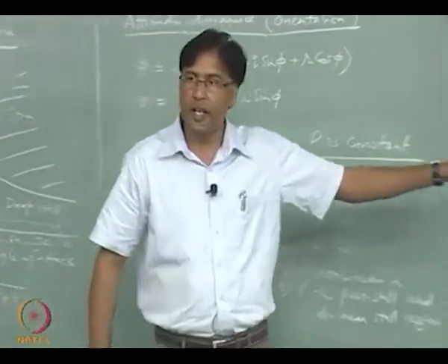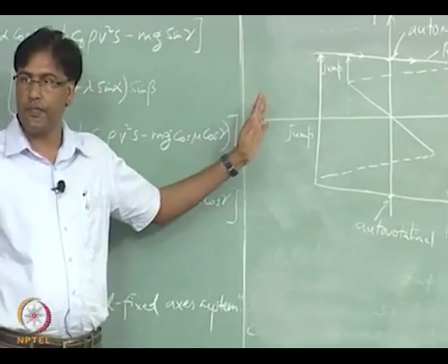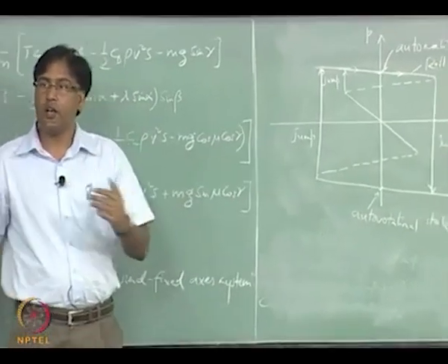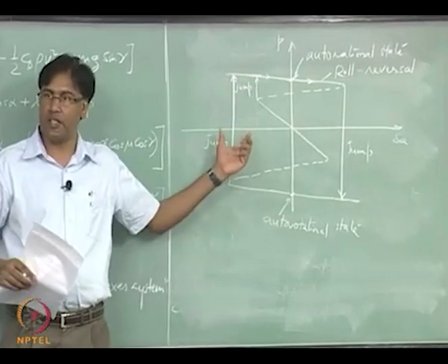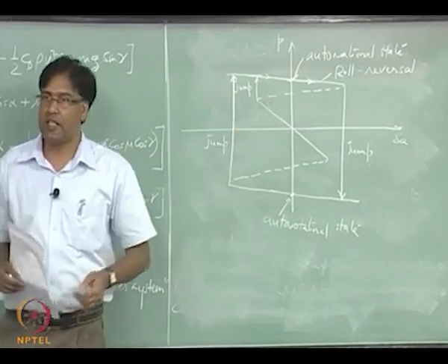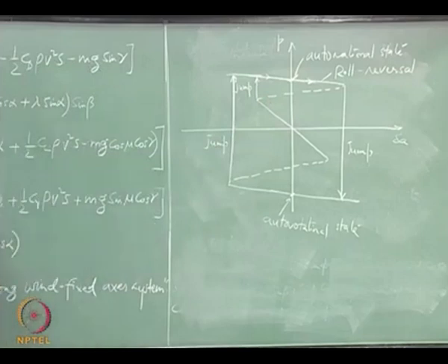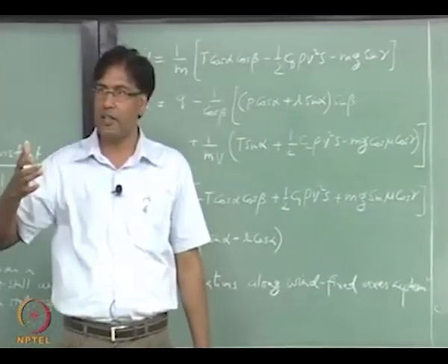This is because of the inertia coupling. But just because it's non-linear, it is going to give rise to side slip, okay, when this happens. So beyond this point, you have a large increase in side slip, and side slip can also contribute to the roll. Look at the vertical tail.